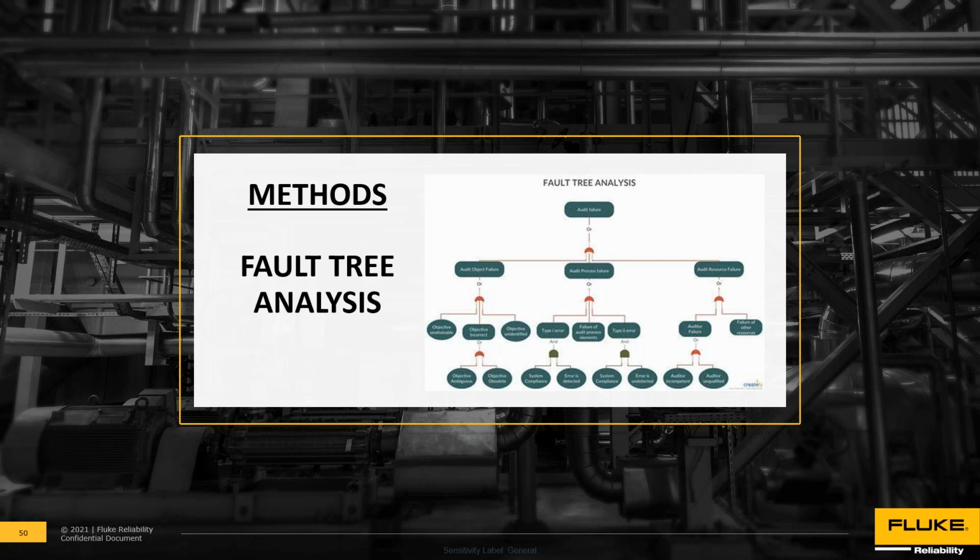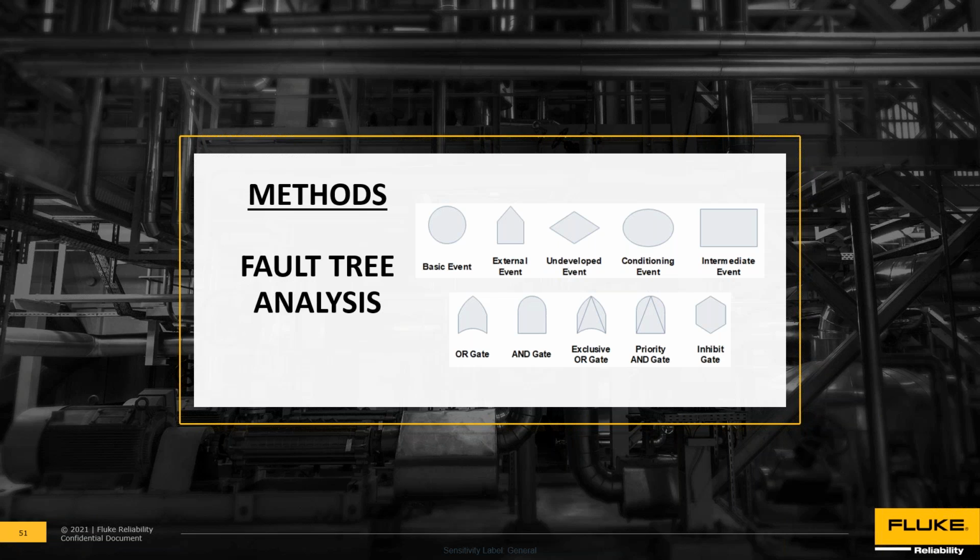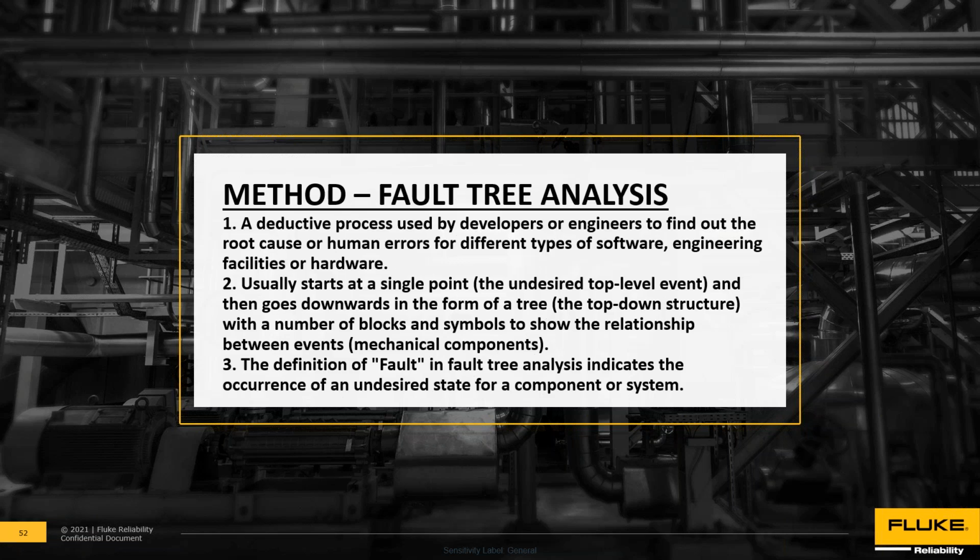I look at it like an FMEA, which probably most of you are pretty familiar with, more of a proactive approach. You look at, say, a solenoid valve, how can it fail? It loses power, it sticks, it's not lubricated, all those kinds of things that go into FMEA types of things. This is like that, more of a proactive RCA, if you will. But I think there's a use for it, and at least understanding that it could be a tool could be useful for certain problems, particularly if they're bigger problems. And here's some symbols that they use in that analysis. So it is a deductive process.